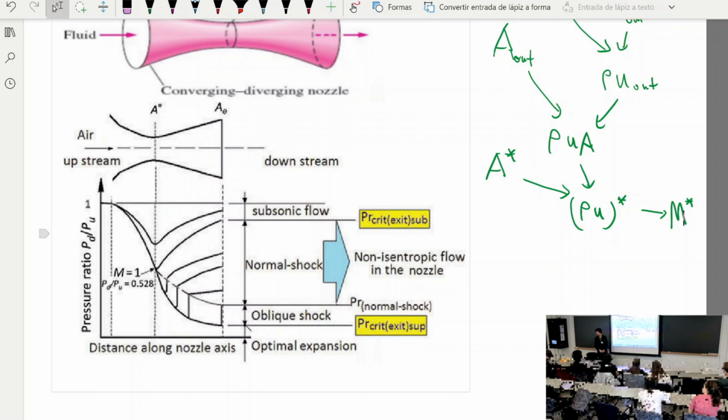Okay, so let's now discuss what's happening over the shock wave. The shock wave, first of all, we have to understand is not isentropic. Why is that? It's because the shock wave is very thin. If you ignore viscosity, you are actually going to derive a shock wave that's infinitely thin, zero thickness. But in reality, that's not what happens. In reality, there is molecular motion. The average speed of the molecules is actually faster than the speed of sound, several times faster. So the molecules actually move across shock waves.